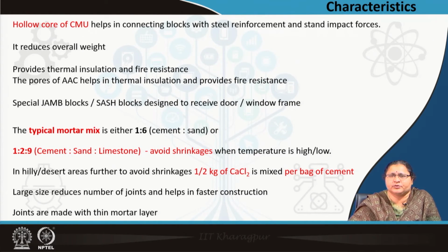Then the proportion becomes 1:2:9, and it is mostly used for desert areas and hilly areas, where further shrinkage can be controlled by using calcium chloride, half kg of calcium chloride per bag of cement.